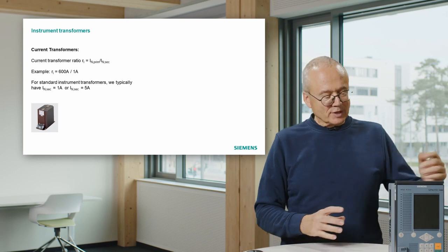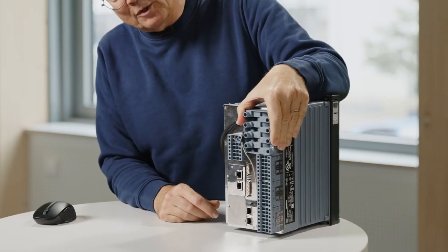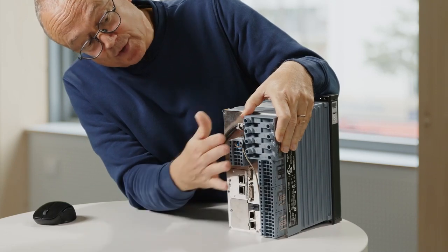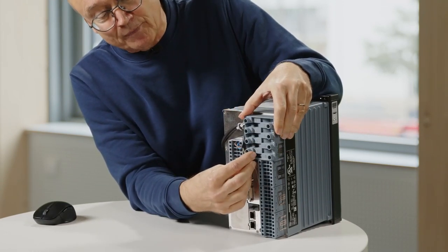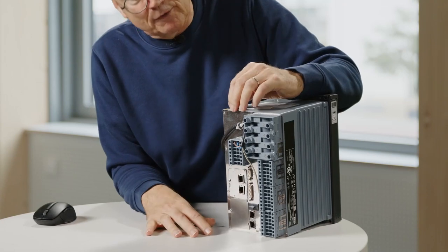And that is the reason if you look into our protection relays, that is a terminal block where the current is connected. Actually, you see 2 things. You see the terminal blocks where you connect the current are much bigger than the other terminal blocks. And the reason behind that is that they must be able to carry the high current. Nominal current 5 amp. Normally the devices have to be tested to withstand 100 times nominal current for 1 second. And that would mean 500 amps for 1 second. And you can imagine for that you need bigger screws, and of course you also need sufficient cross-section.